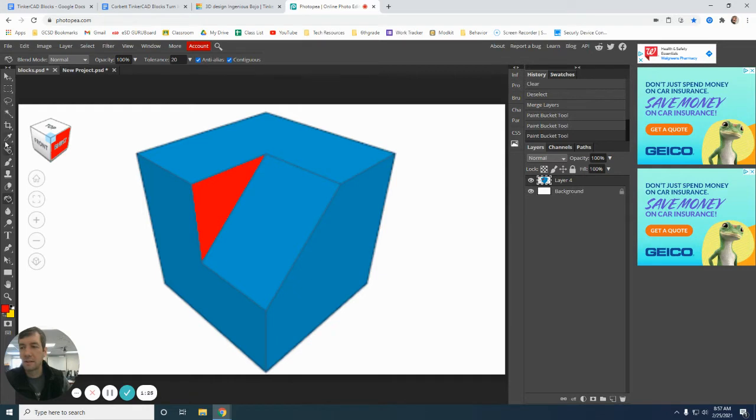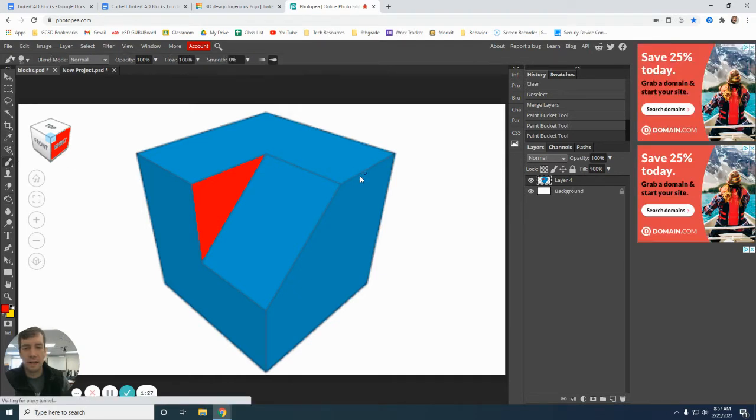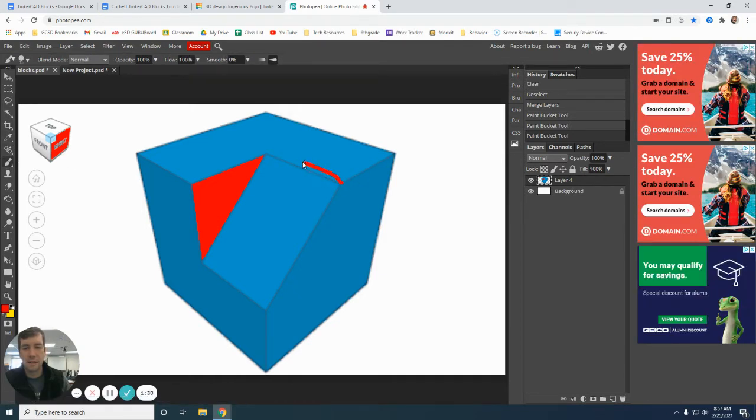Let's take another look here. If I draw a line, the distance from here to here is about halfway. Because then if we do this side from here to here, they're about the same. This distance is going to be 45 millimeters because the block is 90 and half of 90 is 45.